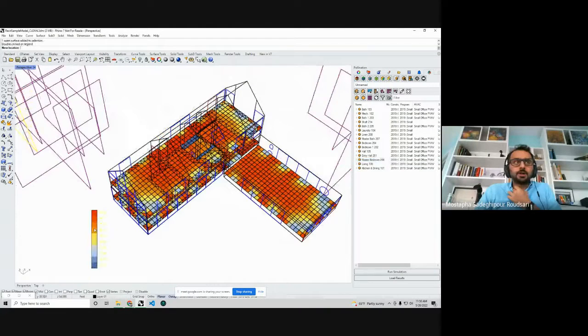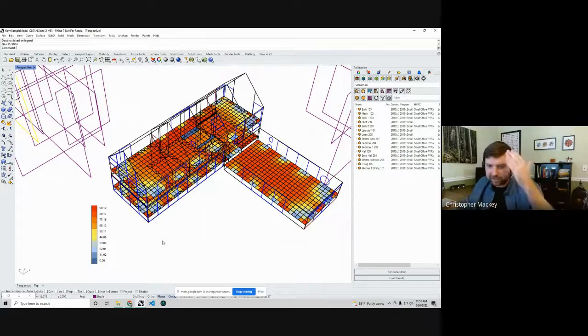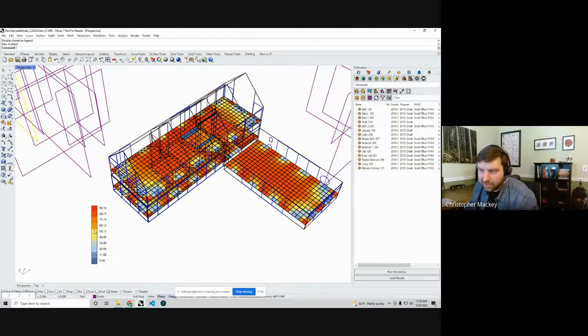Right. So just one comment. That's useful daylight illuminance. I know Chris is trying to wrap it up. Yeah, I'm sorry, UDI. I'm going kind of fast. Yes, this is UDI. It's going to show you the sweet spot between not too much and not too little light. And you see these results are percentages.